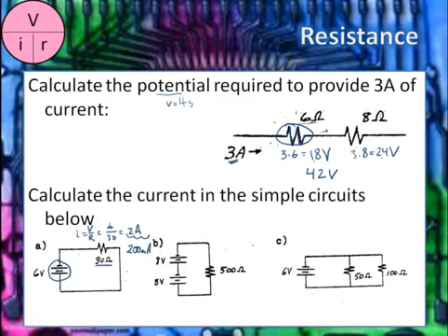Here, I've got 2 batteries set up right on top of each other, and so if we call this maybe 0 volts, then in between here I'd be up to 8 volts, and up at the top I'm at 16 volts. And so those 16 volts are able to push current through the 500 ohm resistance.